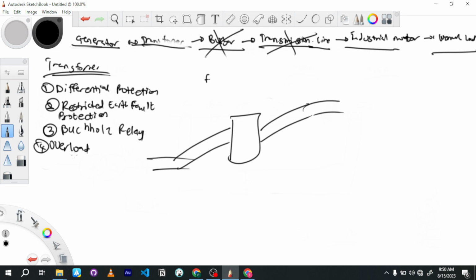So we have generator protection. Both classifications are five, right? Overload and overcurrent, stator fault, rotor fault, failure of prime mover, which is mechanical fault, and failure of load circuit. These are all the protection schemes you can use: overload, overcurrent, overvoltage, undervoltage, all of these. We look at a few of them. For the generator, we use differential protection, sorry.